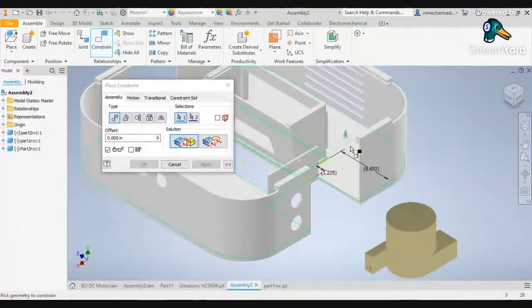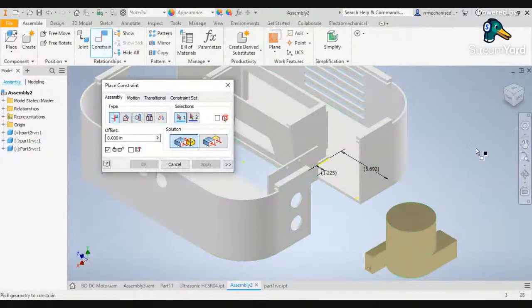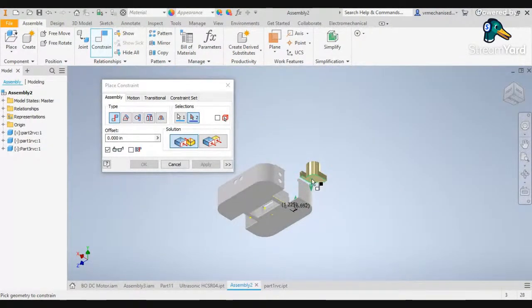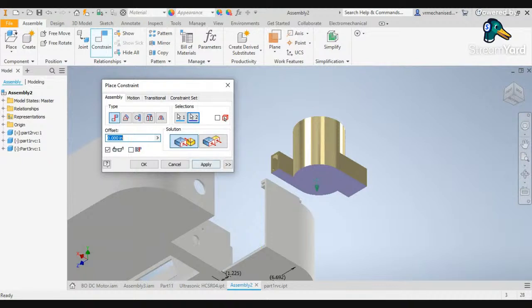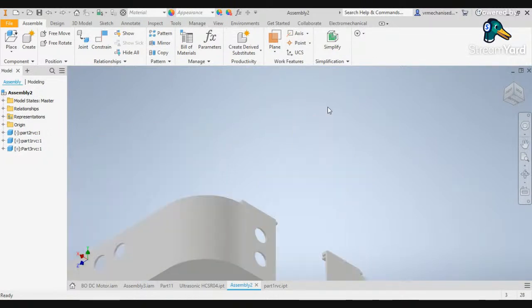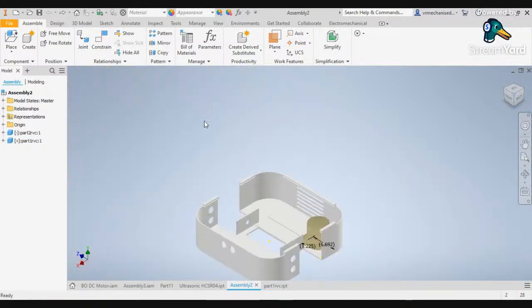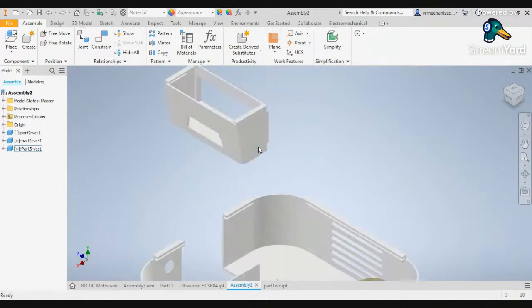While assembling, sometimes due to the surface properties, if you don't give them correctly, the other parts may get removed, but don't worry regarding them. Again you can fix them. Similarly, the first surface is this thing, click on it. Next is the bottom of the surface, click on it, apply. If it's not applying, then just do one thing, Control Z, go for the previous assembly part, go for an arrow over here.